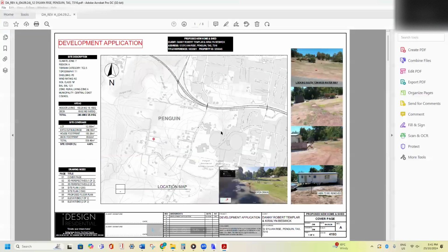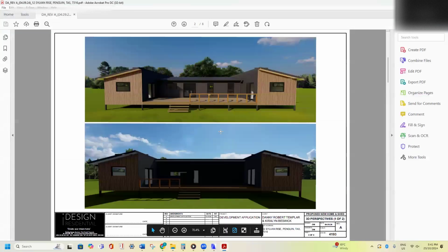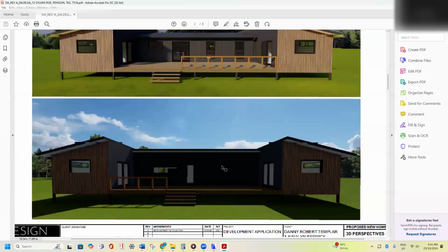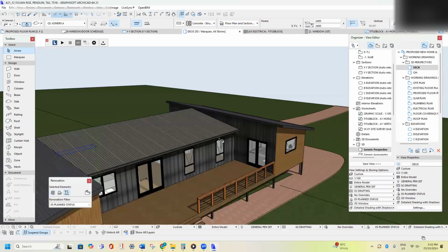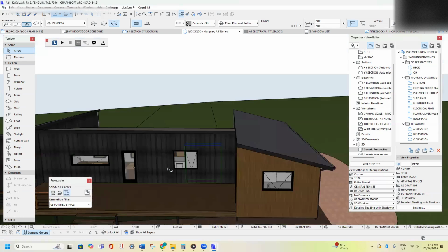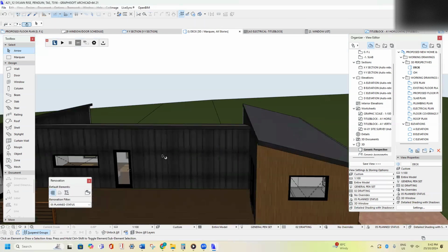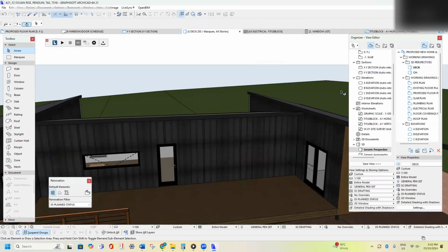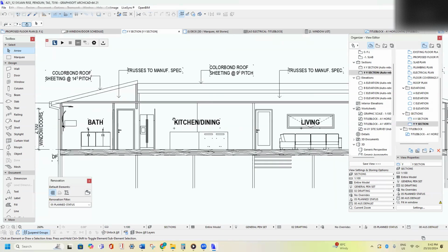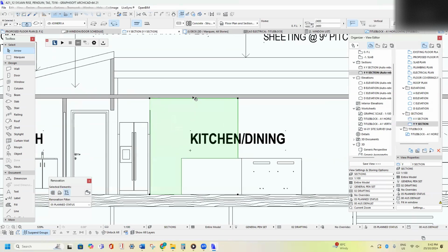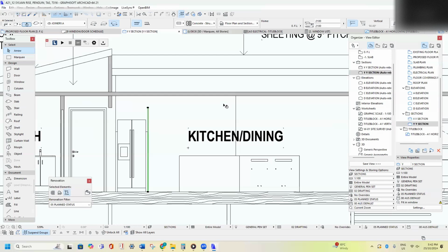On the DA floor plan, I didn't actually have a window showing there. So that's actually another window that needs to be removed. Delete. Now if I go back to section Y, there's not that awkward half a window showing now, because I have a cupboard here going all the way up to the roof.